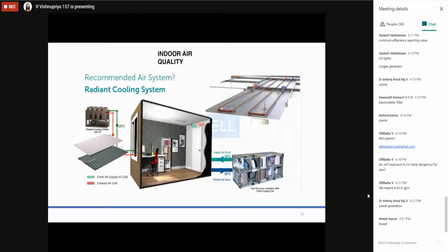I'm adding only 7,000 CFM. Earlier it was 10,000. Now I'm giving 7,000. By reducing the air quantity, I'm going to have efficient IAQ, right? If I have a much lesser air quantity, the contamination, the crisscross area, the turbulence, I'm just avoiding it. So this is also one of the good selections.